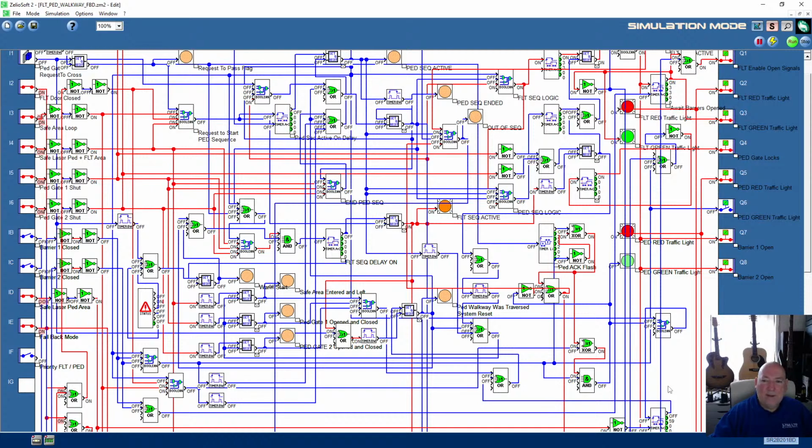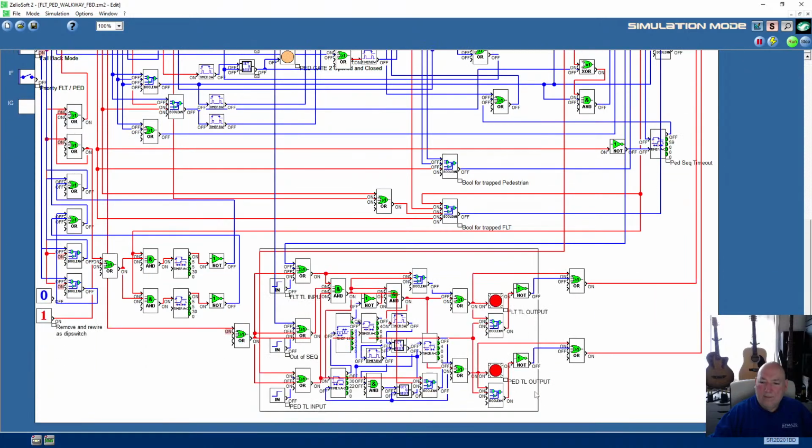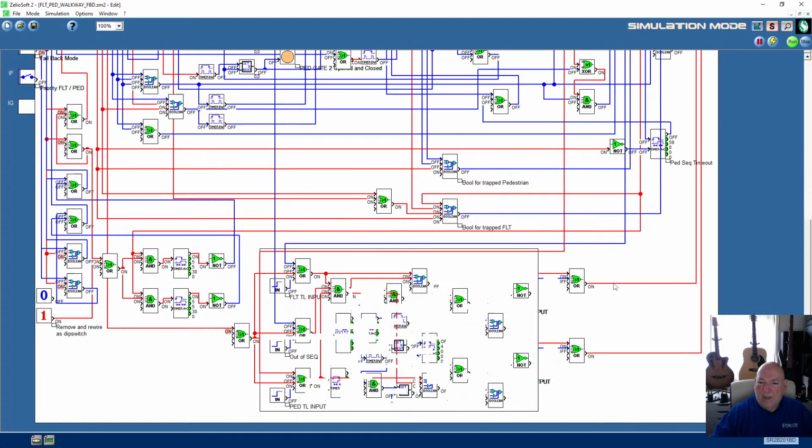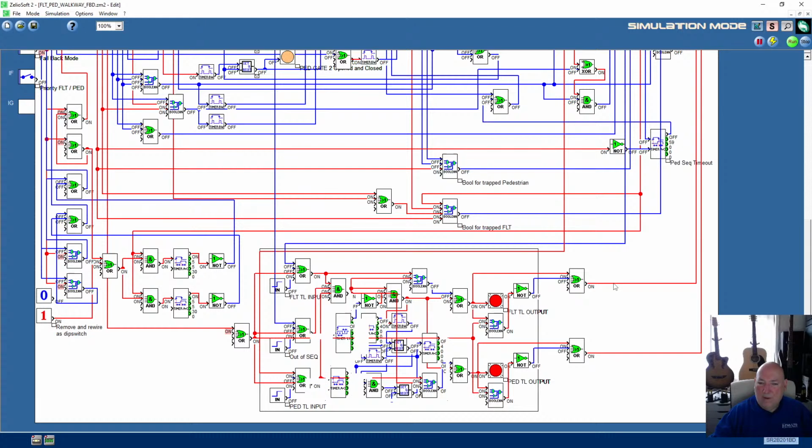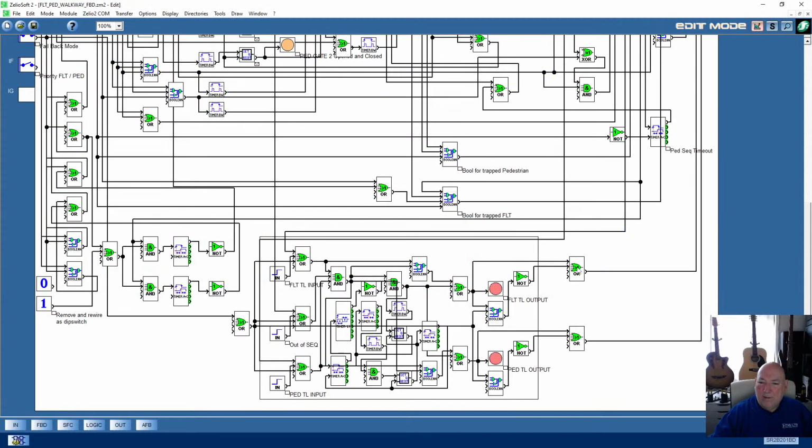Nothing's happening. Let's have a look down here. We're switching. Right, so we need to, yeah, might not need this. We need to know when that's on to switch an output. Yeah, we are switching an output when they're both on. But the one switches off, the one switches on. So you never see a difference. So I think we need an exclusive OR. Yeah, we need an exclusive OR. So that needs to be swapped for an exclusive OR.